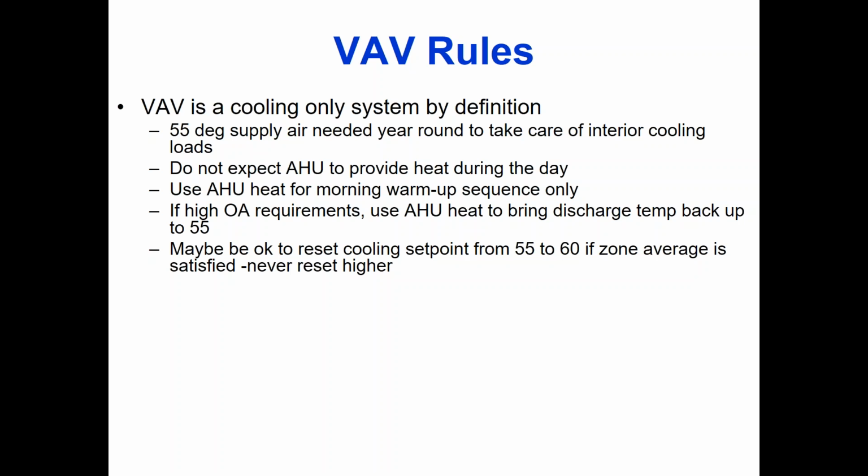A morning warm-up sequence of operation is force all the dampers in the system wide open to 100%, ramp the fan up, and turn all stages of heating on and blast the space. That's what happens for morning warm-up. That's what happens for rooftop occupied heating. So you're normally not going to want to do that. Now there's the tempering thing that Ben asked about earlier, and that's a different discussion. But normal heating, for purpose of heating the space, don't try to do it with the air handler. It's not going to work at all. I've never had a job that worked that way.